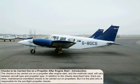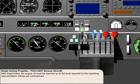The particular checks that we are about to examine are those for the single-acting propeller fitted to the Piper PA-34-200T Seneca aircraft. After engine start, the engine oil must be warmed up to the level required by the operating manual before any checks are commenced. The checks form part of the normal after start and before takeoff checks. For the sake of minimizing confusion between gauges, we, in this demonstration, will concentrate only on the left or number 1 engine.